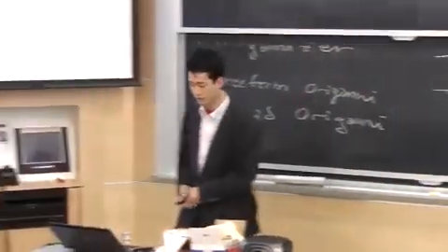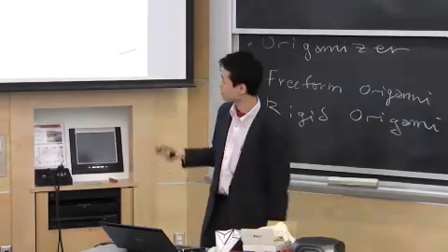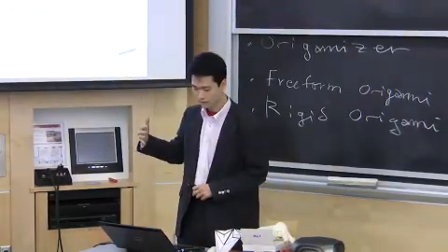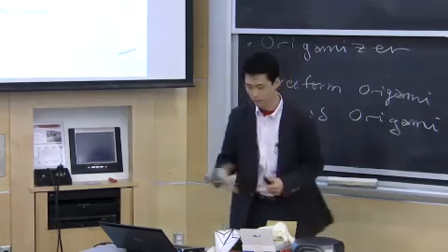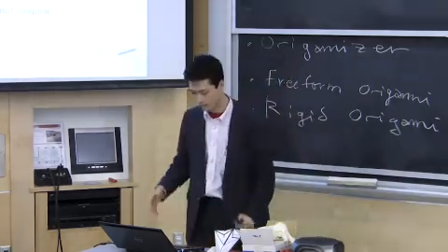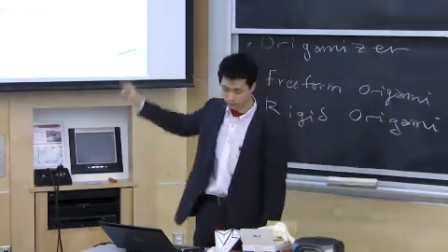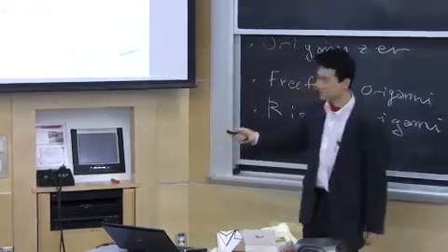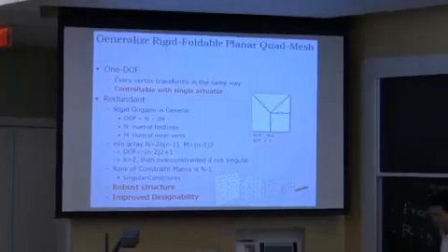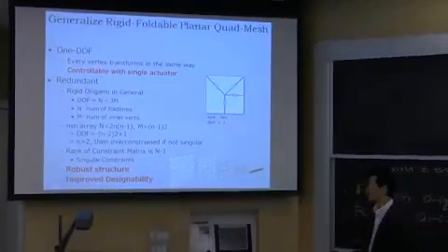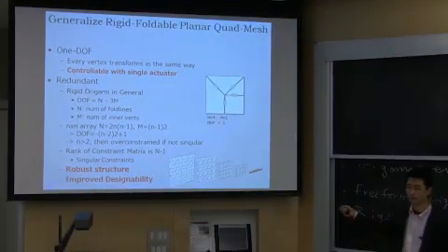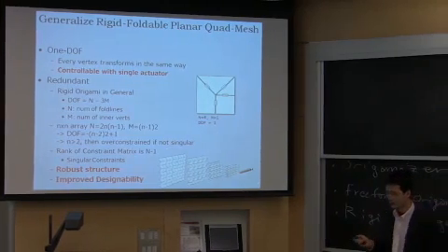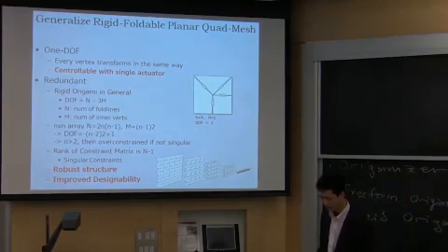And then you will have a problem here because this folding angle and this folding angle contradict, in general, so that you cannot make an array of folding by a quadrilateral mesh. However, as you can see from this figure, there exist examples like Miura-ori that give 1 degree of freedom motion. This is actually a very interesting thing happening.